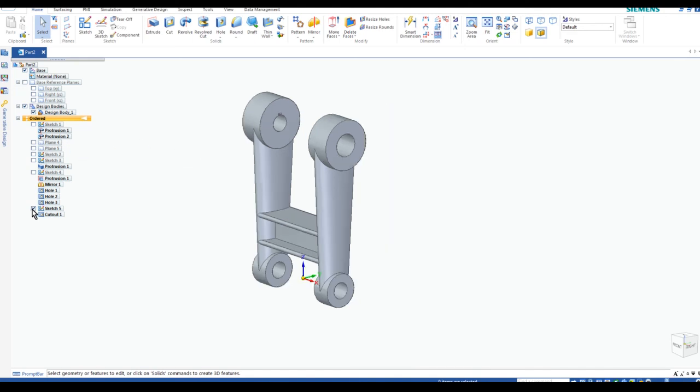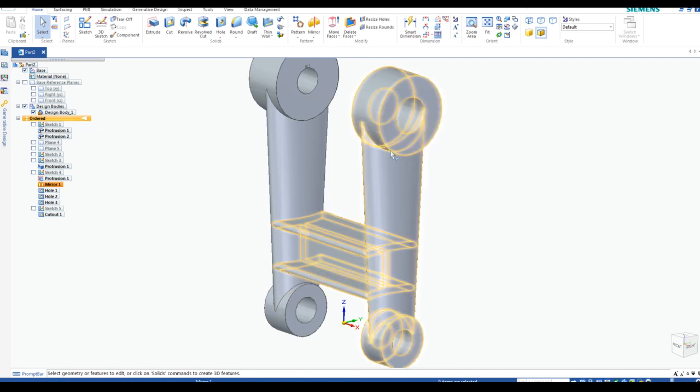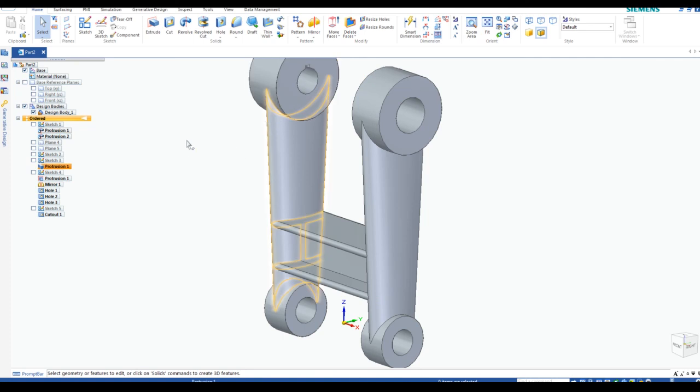Okay, let's turn off the last sketch. Our very last thing to do is add our final secondary features, and our secondary features are the rounds. Most of the rounds are 3 millimeters, but let's see what we've got. The bottom here is going to be 1.5. The outside edge is also 1.5. It's going to be 3 up here and 3 here. So let's take a look. We're going to go to rounds.